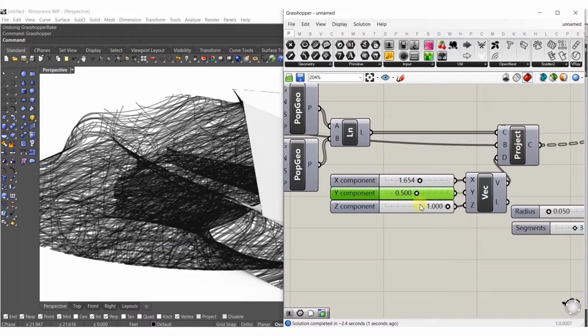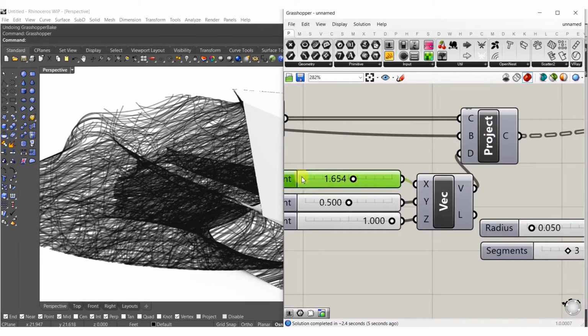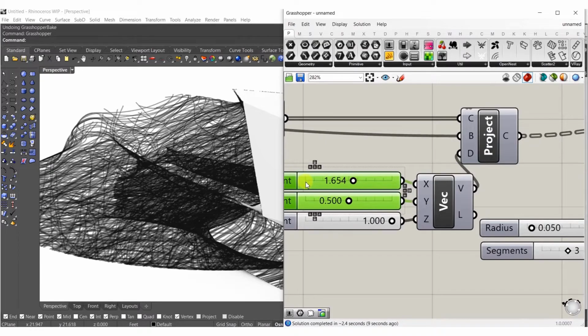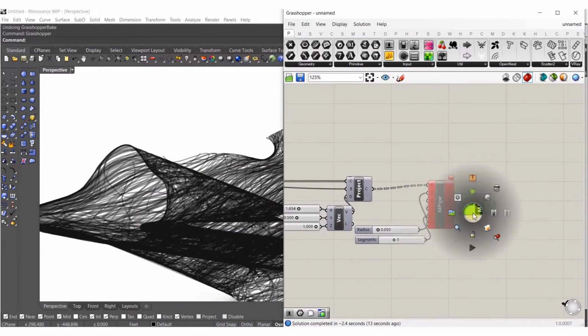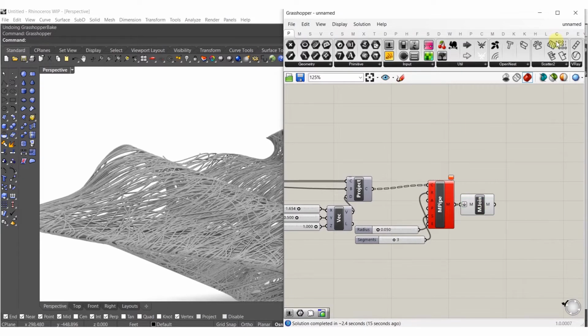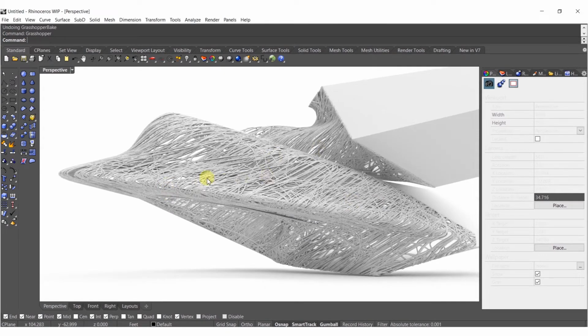And if you notice up here, we're missing a portion. That's just because the projection is missing based on our vector. So what we need to do to fix that, super easy, and that's why we put the scale in at the beginning there. So we'll just make the scale of this bigger. So let's do 2.2 maybe. Fill that gap up.